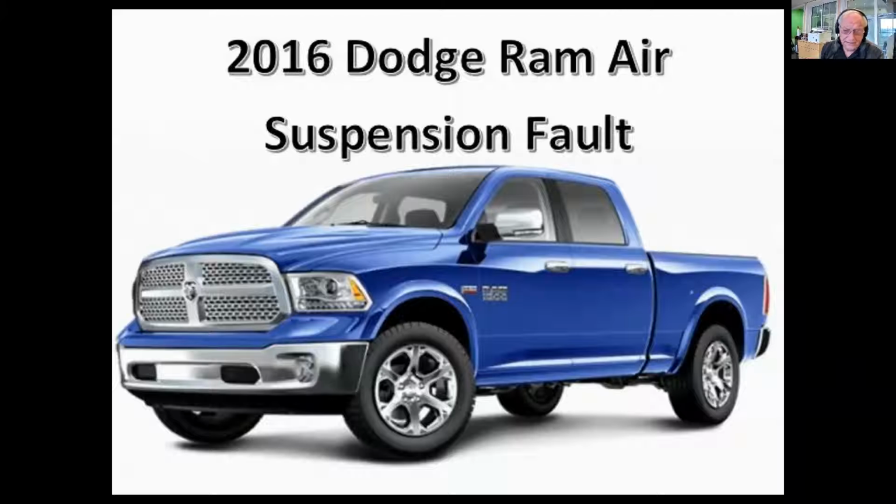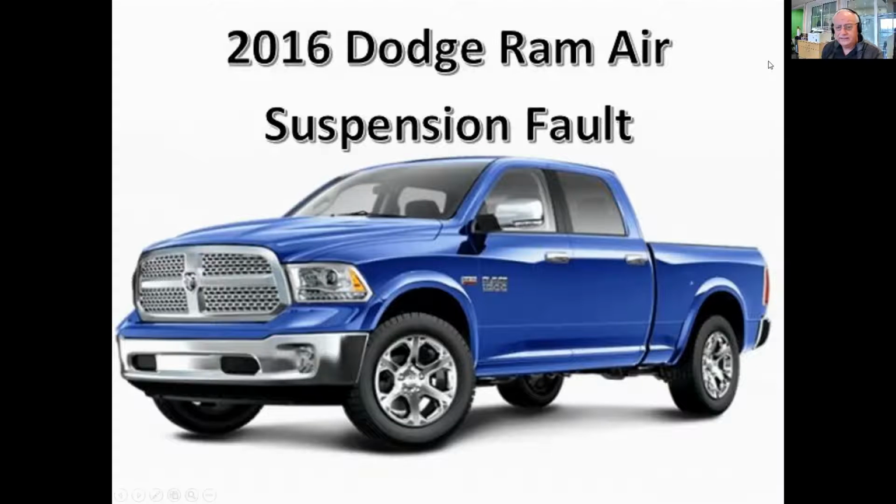Now, the shop that was working on this thing did some work on it. It had a new air suspension module installed on it. It had a new compressor installed on it. They have apparently done a system fill. I think they filled it with air as opposed to nitrogen, which is what you're supposed to be using, but they didn't do that. And they still can't get the light to go out. Apparently it keeps setting the same codes. So they called us to come and take a look at it.